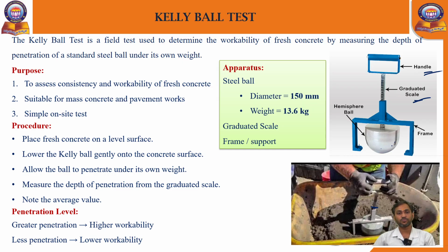Note the average value. If greater penetration happens, it indicates a high workability level. If lower penetration happens, it indicates a lower workability level of the concrete.